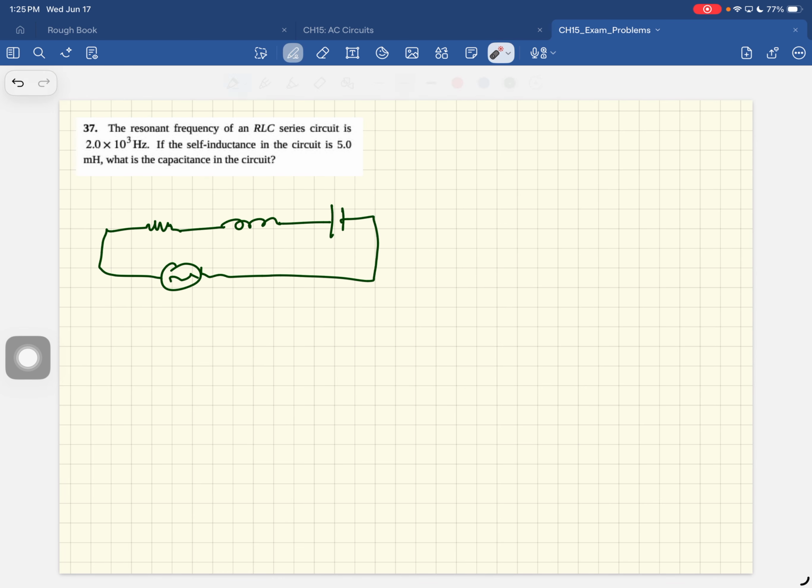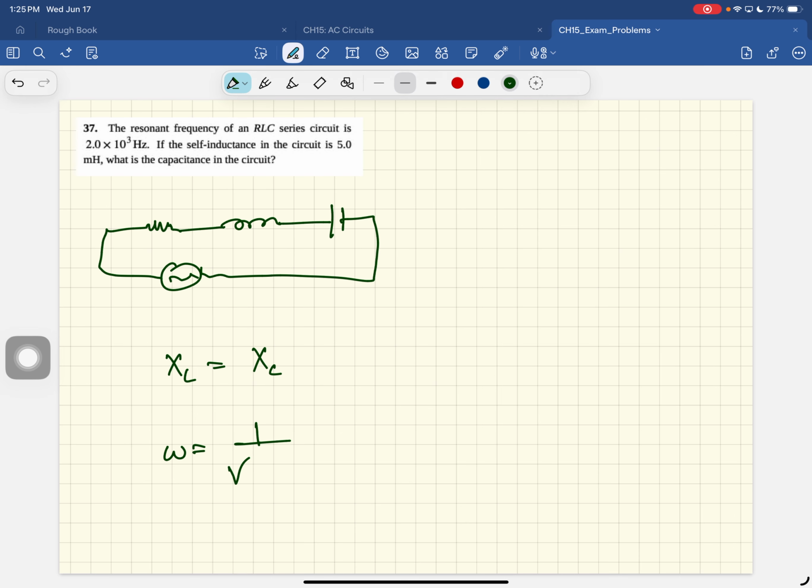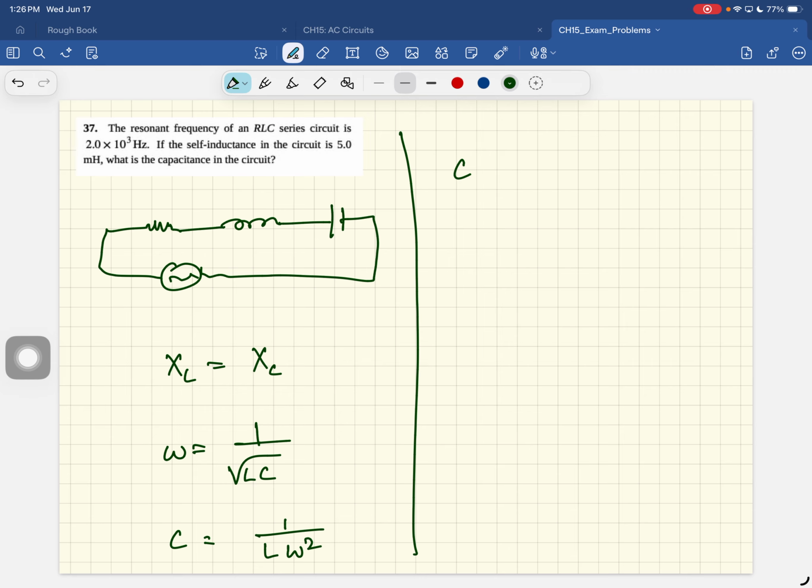What is Q of the circuit? Q of the circuit at that resonance frequency, you're delivering 50 watts of power. And if you get to this frequency, so this is delta omega, okay? And if you get to that frequency, the power delivered will be half as much. Okay, so at this frequency, the power delivered will be half as much.